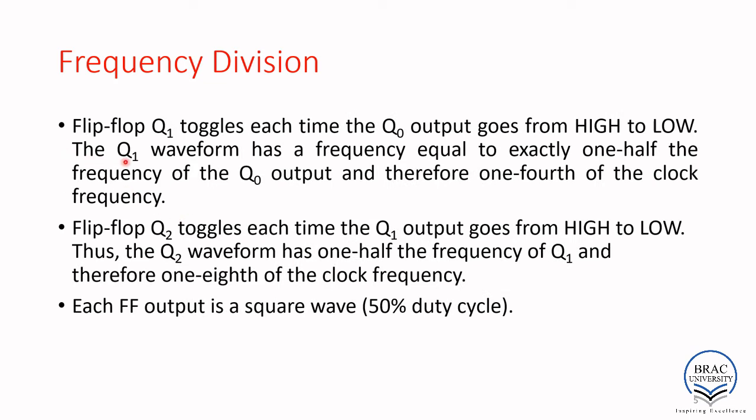So it is saying, after the second it will be 1/4, and after the third it will be 1/8, right? Which basically means each flip-flop output is a square wave, which means it has a 50% duty cycle. Okay, this is very important.